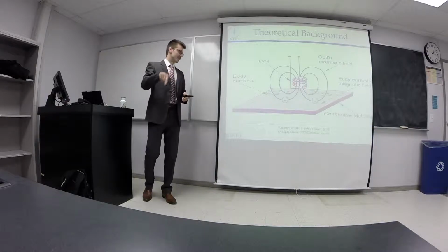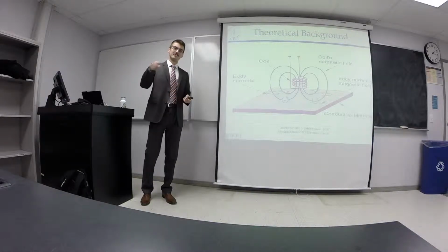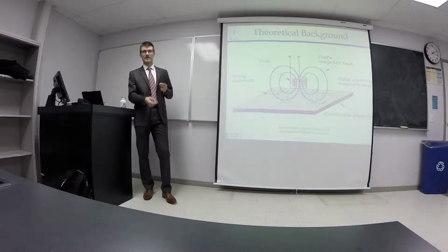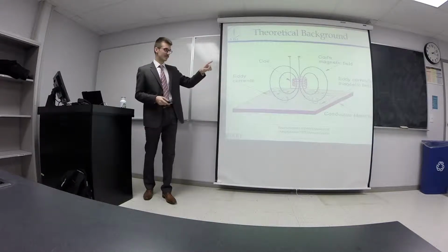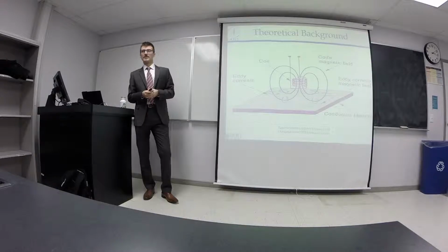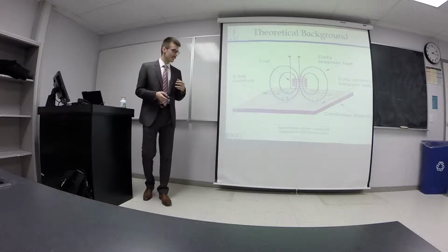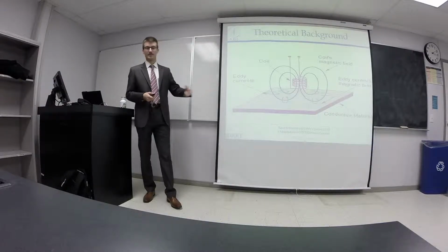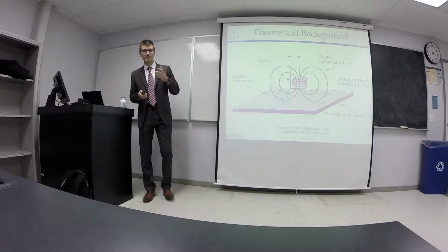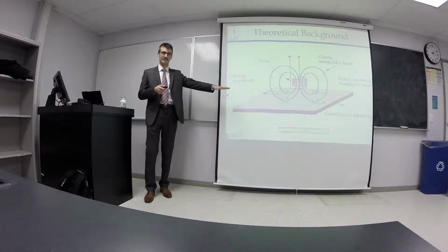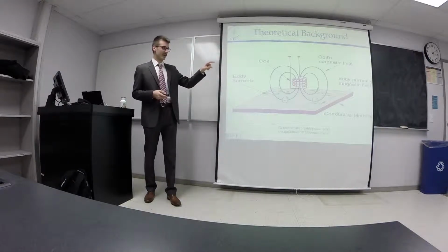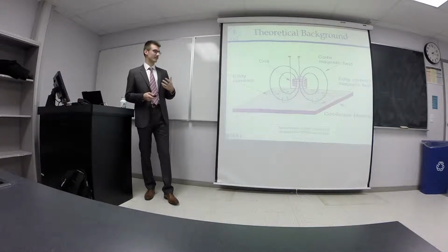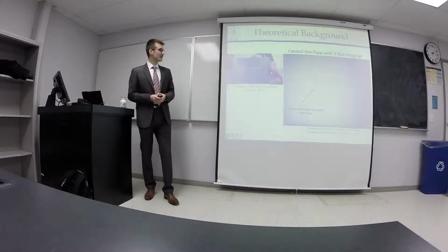They are generated from the magnetic field, and they themselves generate their own magnetic fields in opposition to the coil's magnetic field, and these interact with the generated magnetic field from the coil. These interactions are dependent on the material properties of your conductive material, and they give you very precise feedback on the material being examined. So by measuring the change in resistance and inductance in the coil, you can get some nice information on what you're looking at.